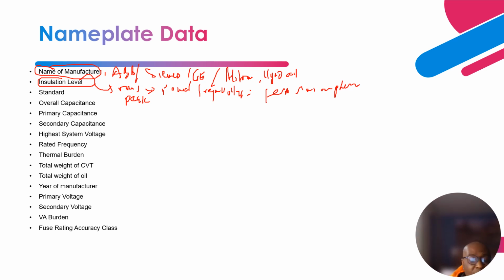If you have inductive elements and capacitive elements in the capacitive voltage transformer, you have an electromagnetic unit, a tuned reactor, and also the capacitive divider, C1 and C2. If these integrate with an external capacitor bank or a reactor in a substation, that can cause it. Reactors are used for this: if you have a Ferranti effect voltage condition at the load end, reactors are utilized to regulate the voltage on that end to bring it to the required level.